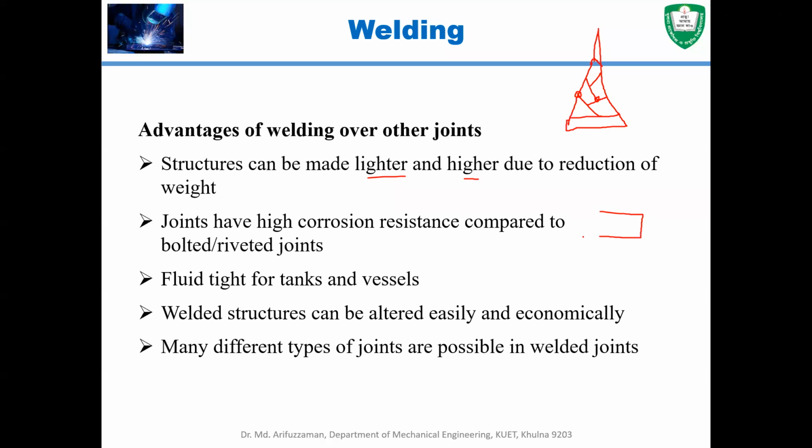For example, if you have two metal pieces joined together with the help of a bolt in this region, how does the corrosion actually work? Corrosion works in such a way that when water particles are trapped in the small corners of the bolt, that entrapment causes the water to react with the metal and form metal oxide.